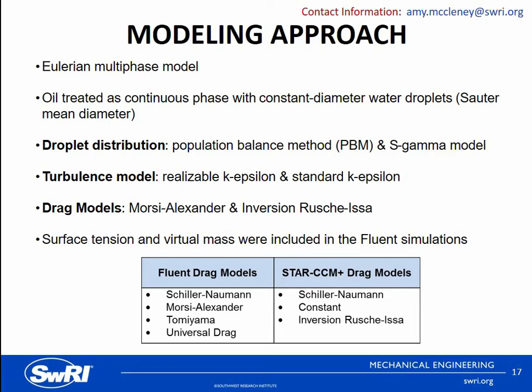The respective models provided a slight improvement in agreement of the simulation results, but only by 1 to 3%. However, the computational time increased significantly. Since adding a droplet size distribution did not significantly improve the overall simulation results within a reasonable computational cost, monodispersed constant size water droplets were used for all simulations.